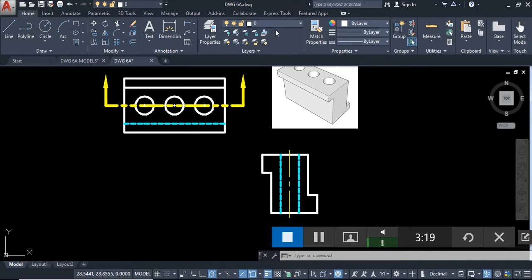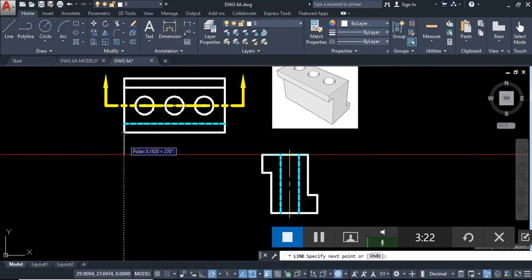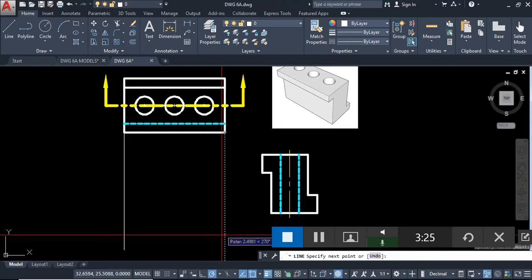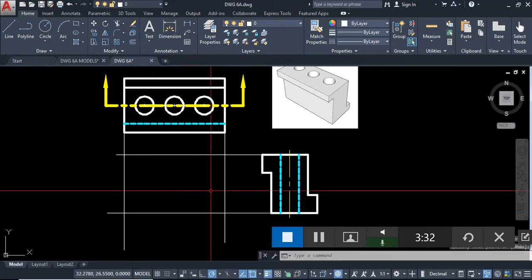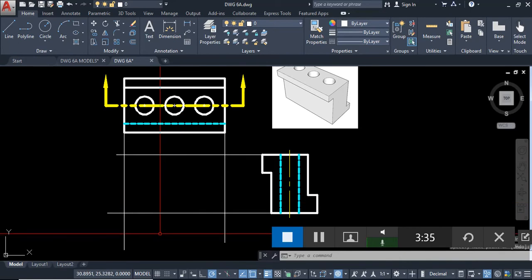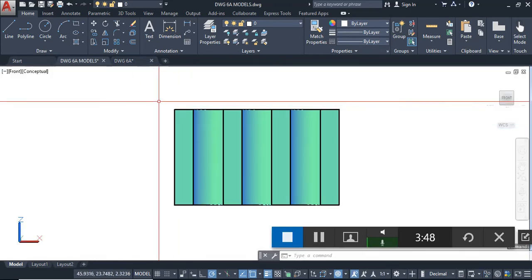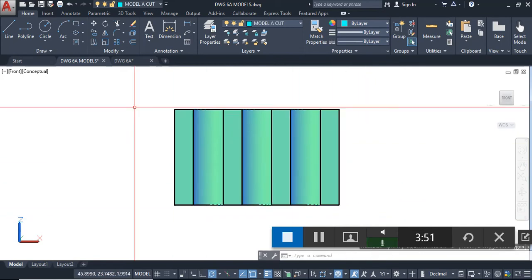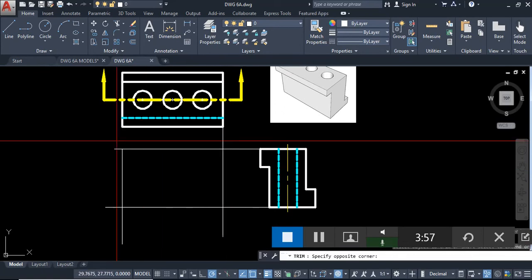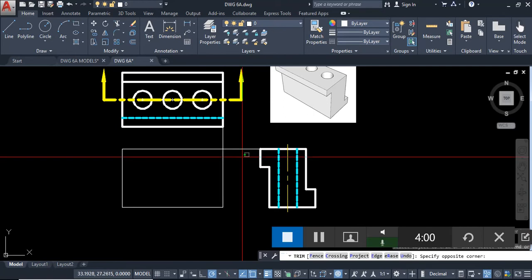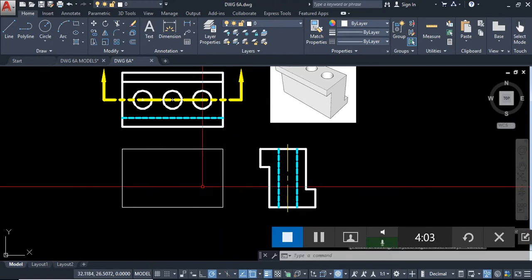And let's talk about how we can set this up. So probably the best thing to do is lightly project some construction lines. Project from there, project from there, project from here and here. And those are the only things we need to project to get the shape we want. Because remember, the shape is the rectangle, the rectangle that defines what we're looking at here. Okay. So we can clean up the rest of that. Of course, when you're doing this with pencil, it's going to take a little bit more finesse.